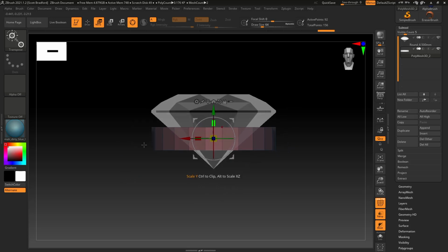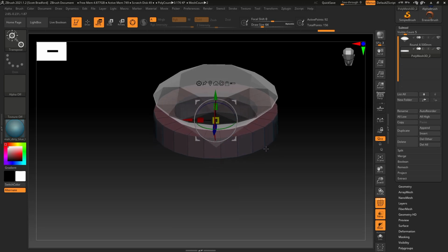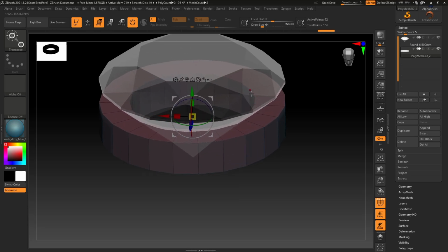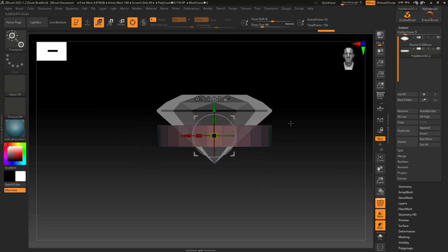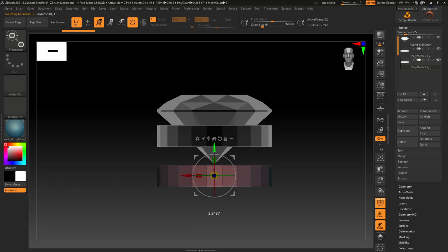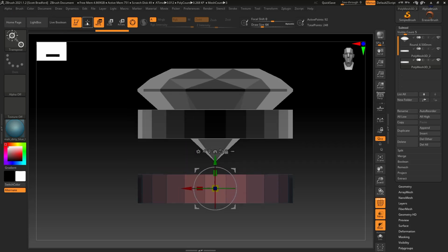So now we've got the top rail, now we're going to do the bottom rail. And all we're going to do is duplicate this. And we're doing this now. We don't want to add our bevel in here just yet because we don't want that bevel on the bottom rail as well. So while we've got this solid, I'm going to go into my subtool palette, make sure that rail is selected, and then click Duplicate, and then use my gizmo to bring that down. I'm going to turn my gizmo off so you can see a little better.